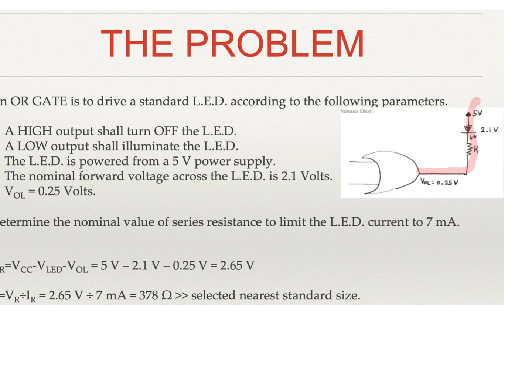Over here, you'll see that I've set, let's assume, the output low voltage. What is that? That is just VCE sat of that lower transistor. That's actually not going to be zero, right? So if you look at this, you can easily calculate the value of the resistor there to give us the current that we want. I'm going to redraw that a little bigger on the next slide.